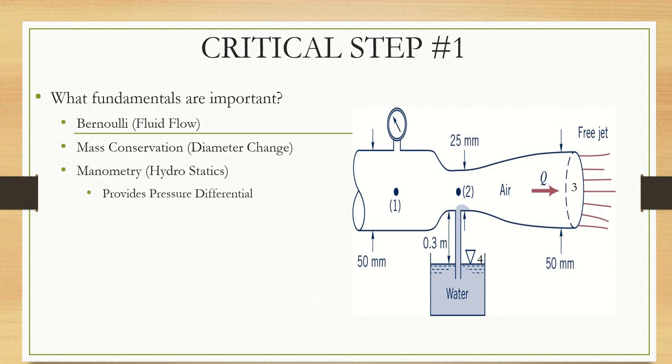So the first thing that we want to do is ask ourselves, what are the fundamentals? We never try and solve a problem without first saying, what are the fundamental guiding principles that will determine the roadmap to solve this problem? Point one, I know that I have fluid flowing in the duct. It's frictionless. It's steady state. So therefore, I know that Bernoulli is an important fundamental principle because I have frictionless fluid flow in the duct.